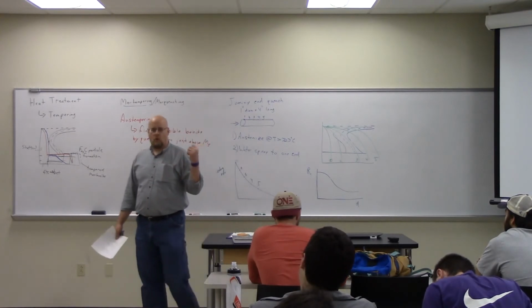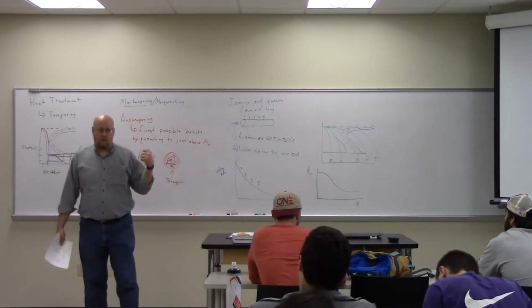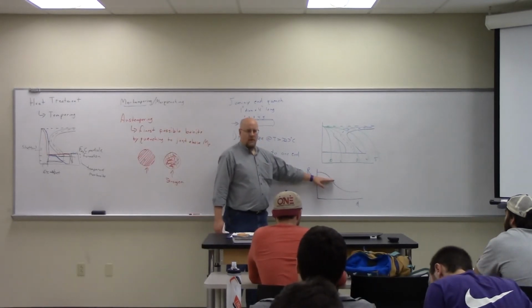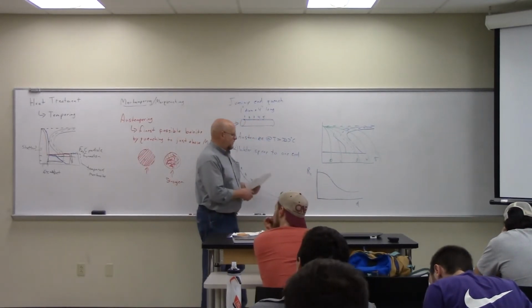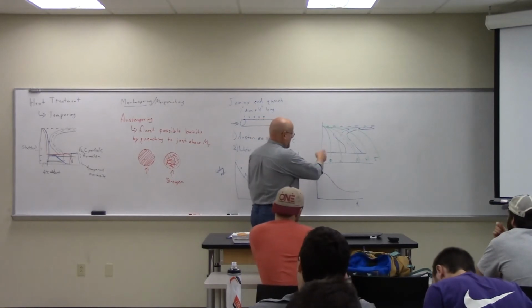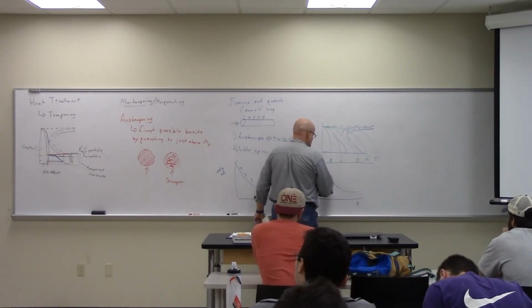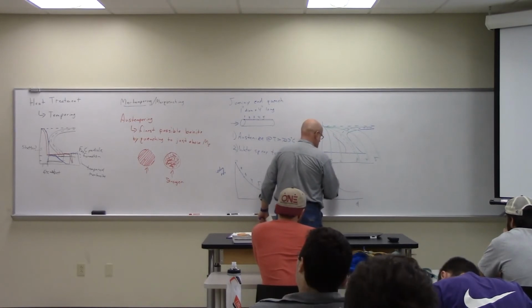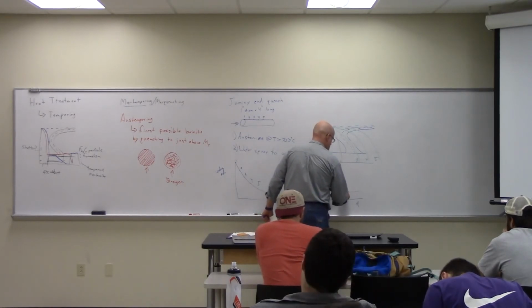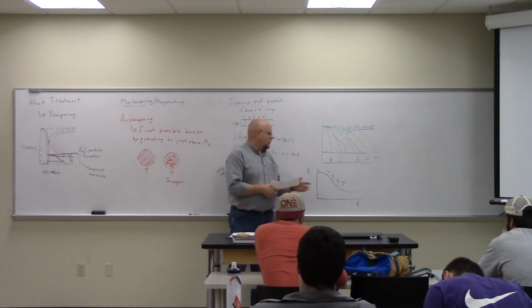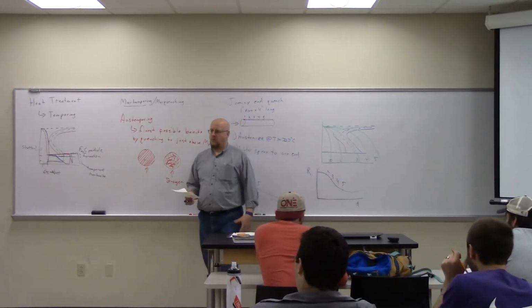And hardness is correlated to tensile strength. So if I know the tensile strength of the material that I need, it's got to be here or above, then in other words, let's say this is 1, 2, 3, 4, 5. I know that I've got to be at cooling curve 3 or above to achieve that hardness.